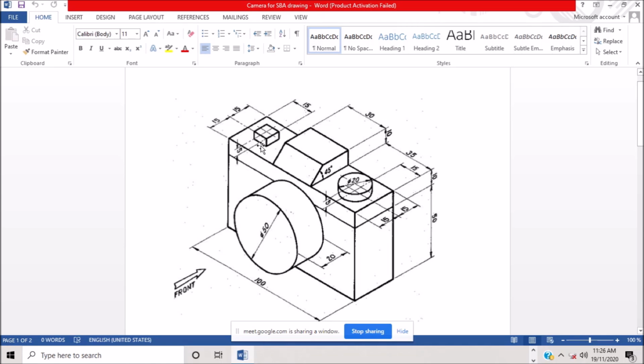In order for you to understand this square, as you see, from here to the center is 15, and from here to here is 15. And we go down at a depth of 5. Because we're going down at a depth of 5, we subtract the 5 from the 15, so we get 10. From here to here is going to be 5. Therefore it's going to be a square of 10 millimeters. Following?